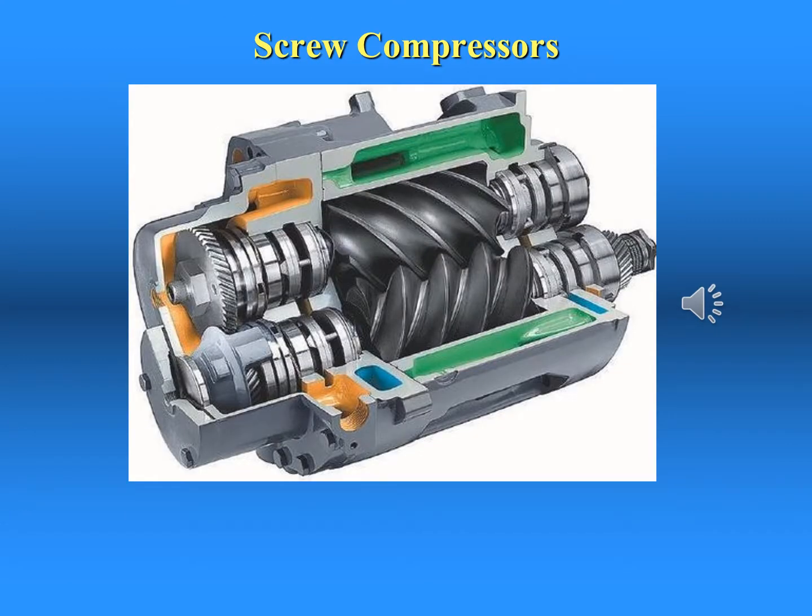This picture is that of a screw compressor. When it comes to maintenance costs, rotary screw compressors have an advantage over reciprocating compressors. Double-acting reciprocating compressors typically require more periodic maintenance than rotary screws. Valves, piston rings, and other consumables on a reciprocating compressor need expensive routine maintenance.